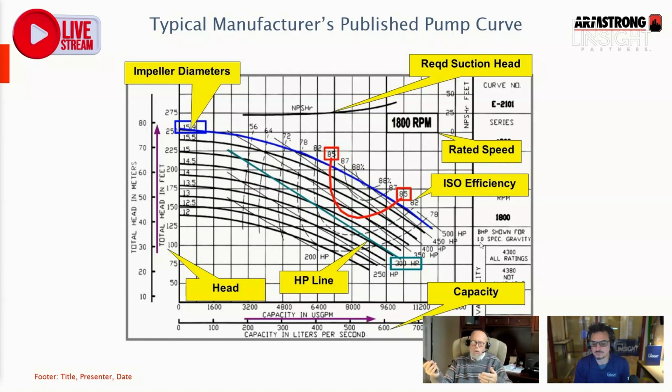Well, as we all know, if I have ethylene glycol or propylene glycol in the system, as I start to drop the temperature, my specific gravity and my density change, which will affect horsepower. In a normal chilled water system, operating at 45 or 42 degrees with ethylene or propylene glycol, temperature really doesn't affect the horsepower significantly, not enough that you're ever going to notice.